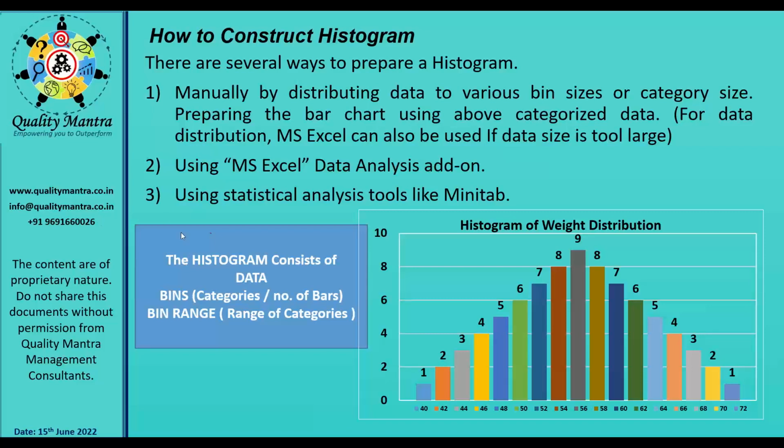So temperature, for example, your temperature range is 1000 degree is the LSL, lower specification limit, and your USL is 1020. Now you need to check where your data is, means 1001 how many times, 1002 how many times, 1003 how many times, up to 1020.